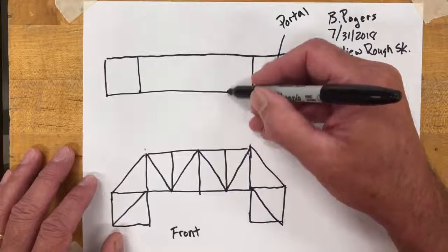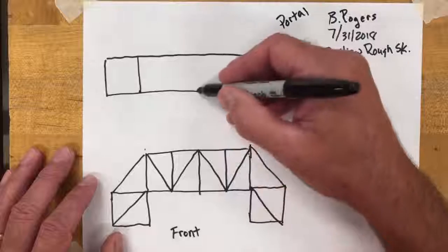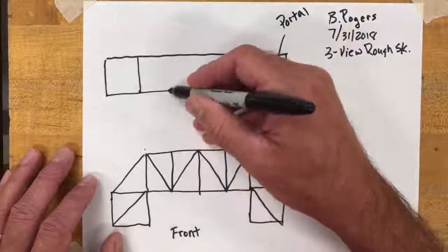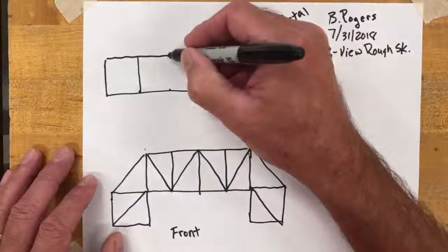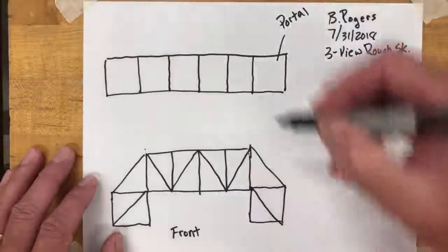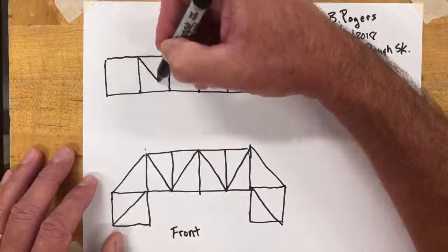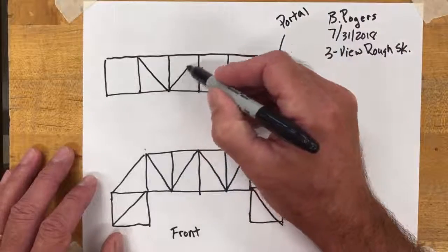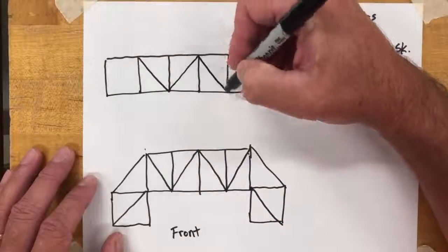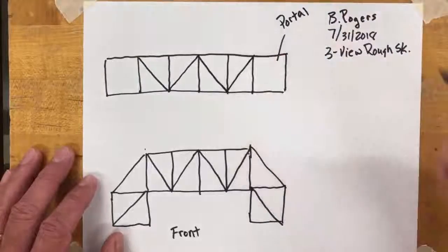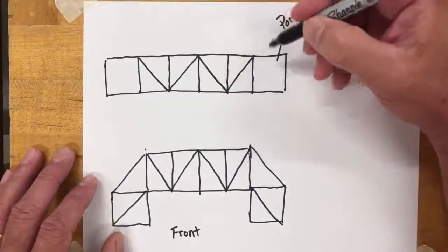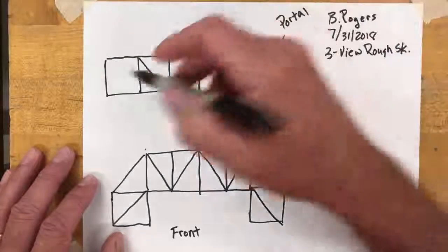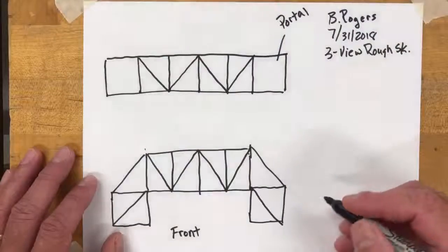So what I'm doing is projecting some points up here from my front view, just like I did previously. And I'm going to divide this into 4 equal pieces. Now I'm going to start dividing these into triangles, because remember we said that triangles were a lot stronger than 4-sided shapes. So I'm going to put some diagonals in there. A lot of you will be tempted to put a diagonal in here, but you can't do that because that's how we're getting on and off the bridge, through those portals.